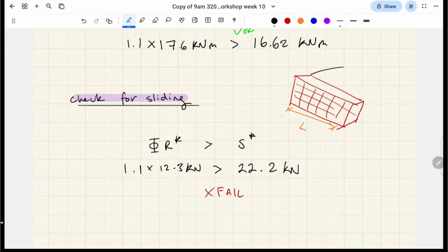And then that's our high elevation of soil. That's our lower elevation of soil, right? We're actually just taking that cross-sectional cut to do our free body diagram analysis. So actually almost all our calcs are per meter run. I've only included the bracket per meter run for my explanations to you guys.